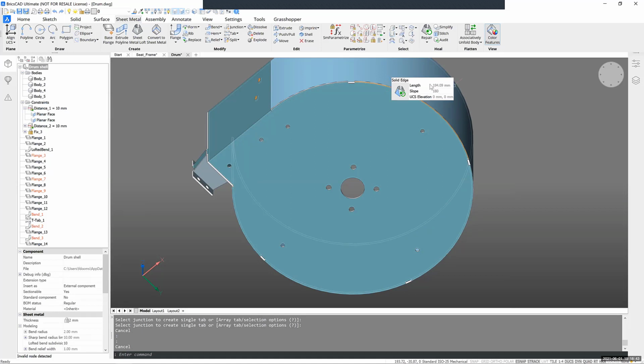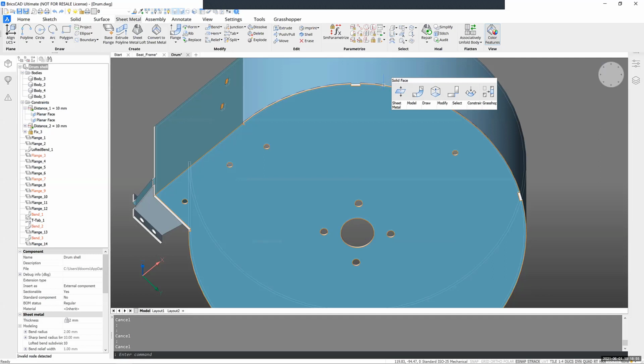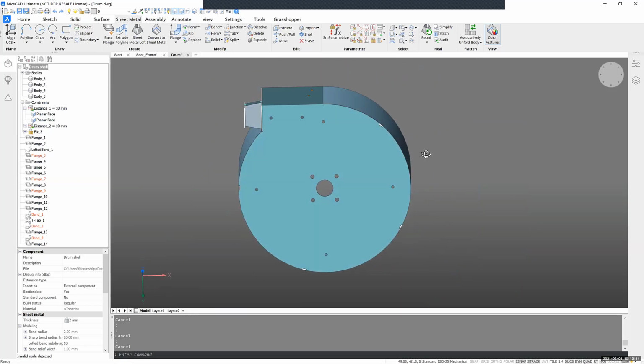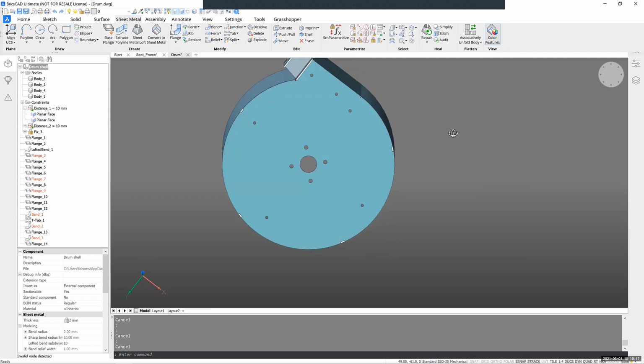It's nicely spaced, 194 millimeters, but then together with this distance 8.11, that will create the 200. So it's from middle of the tab to middle of the tab that we have the 200, which we set at the creation properties. So that's our parameters, let's say.